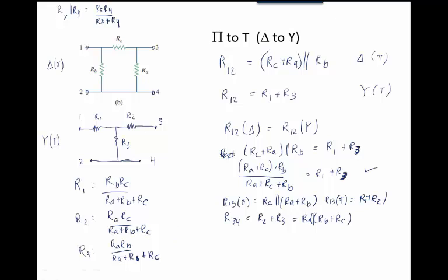So basically what I'm doing is converting this circuit into this circuit. So an easy thing that people like to do to remember it is draw the circuit that they're converting it into in the middle, like so. So this circuit that was original on the outside becomes this circuit that's in the middle.